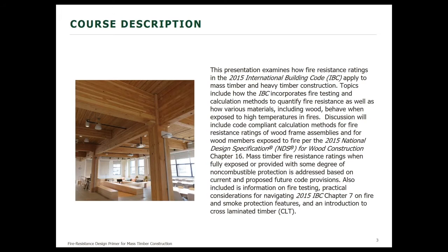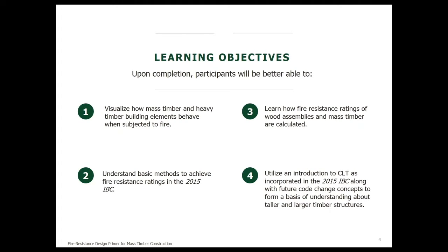And the learning objectives: basically what we're looking at is, hopefully, to give you a feel for how mass timber elements behave in a fire, understand the basic methods that the 2015 IBC recognizes for achieving the fire resistance rating of wood assemblies, learn about the calculation methodology for wood assemblies and mass timber, and learn a little bit more about CLT and the future code change concepts related to taller and larger mass timber structures.